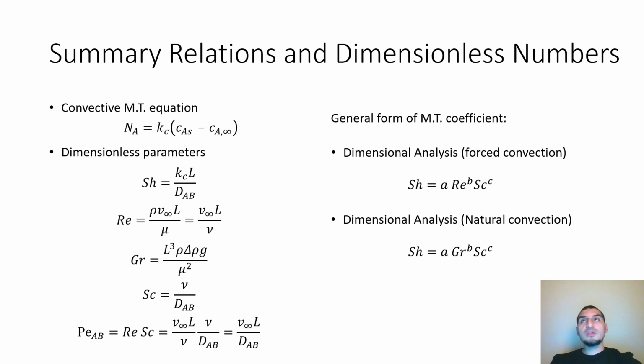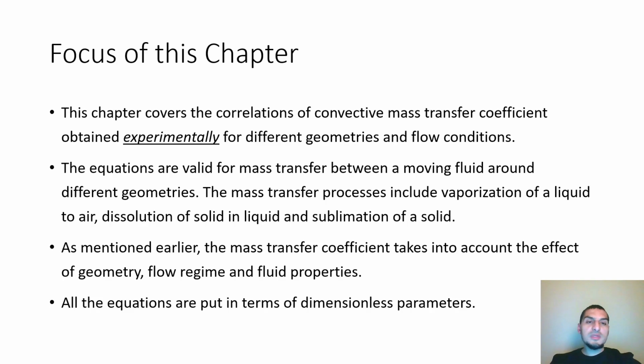If you recall in the previous chapter 27, we always had problems with the mass transfer coefficient given. So we had it as kx, kl, kg, or ky, whatever the shape or units of the mass transfer coefficient, but it was already given, and that's why we didn't bother to calculate it. The only trick that we had was to get another form of the mass transfer coefficient of the same phase, to get kl from kx or kg from ky, something like this. But in this chapter we will be more concerned with calculating the mass transfer coefficient itself.